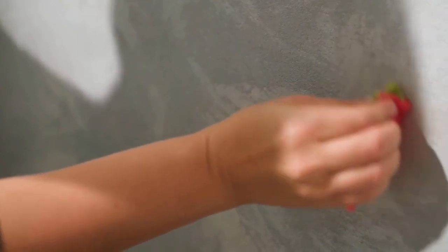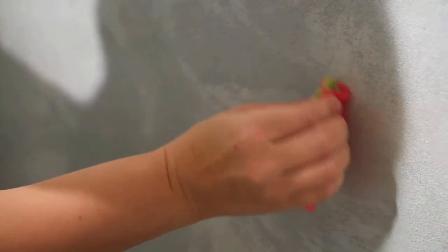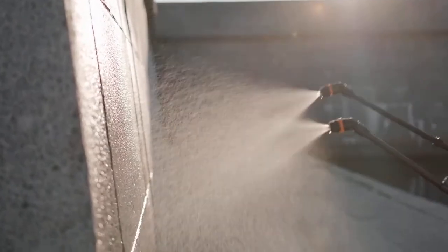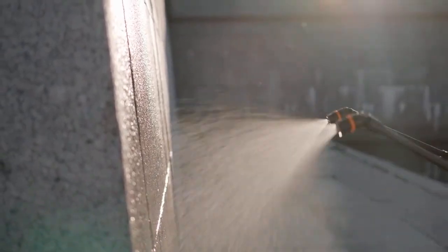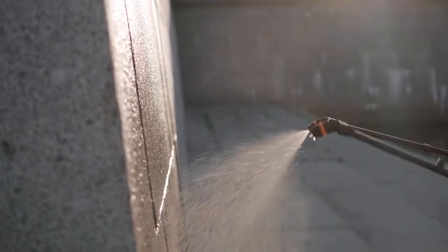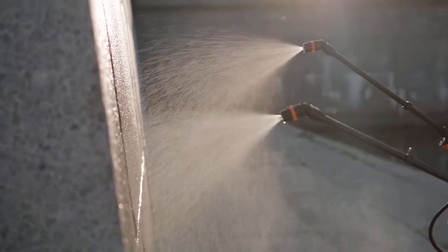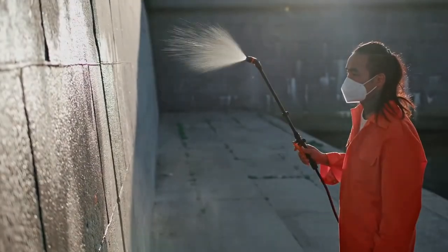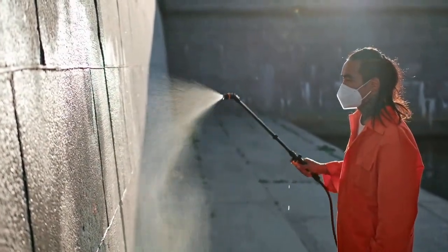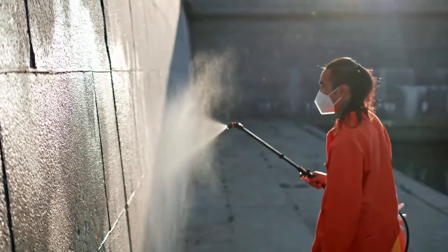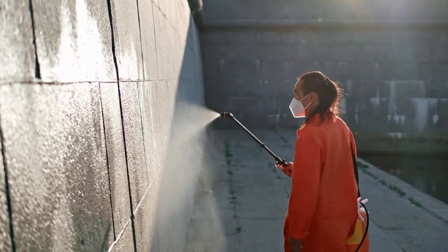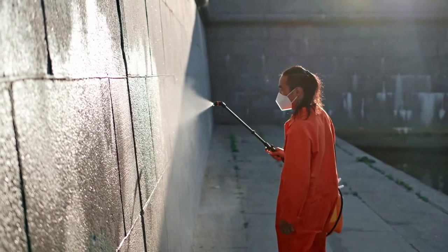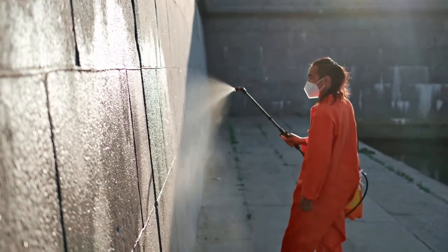First we need to do the surface preparation, as for any architectural finish or any architectural work. Whenever we start, we need to do the surface preparation. So what is the surface preparation? First we need to clean the wall, because after plaster there may be impurities, dust, loose particles, oil or grease. If these are on the plaster surface, then the white cement putty cannot work properly. So first clean the wall and remove dust, loose particles, oil or grease using a wire brush or sandpaper.